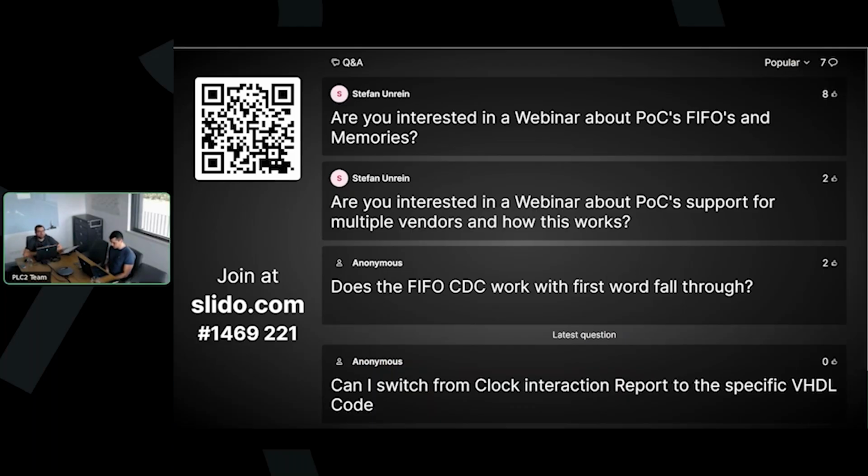The important part is how often you want to read the error counter and how often it's incrementing. If it's just about having the latest state and you can afford 3 to 4 clock cycles for synchronizing, sync vector is okay. In case you want to see all increments in between and they're not linearly incrementing, they are hopping like +5, +10 and so on, and you want to see the intermediate states also of this error counter, then we're talking about continuous data, and then you need a FIFO. Otherwise, if it's just having a look at the latest state that was synchronized, sync vector.